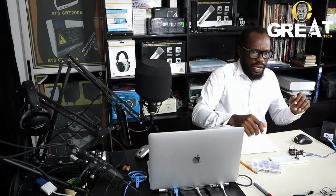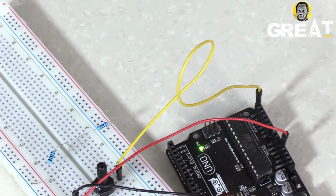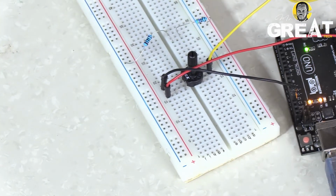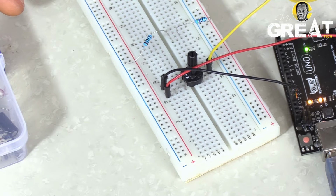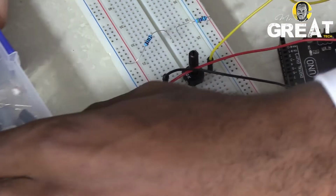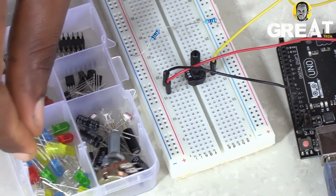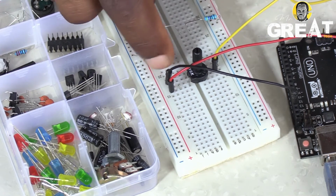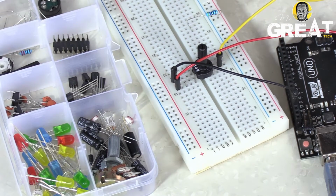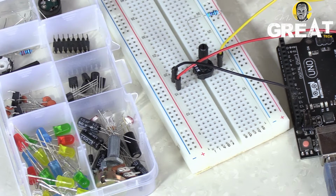Let's connect the hardware, and you have your LED, your light emitting diode. Okay, let me hook up. Let me remove my Arduino so that it's easy for me. You have your LEDs, your light emitting diode. Okay, so you have the red one. Then I have two resistors there, and I'm going to pull out one, the 100 ohms resistor. I'm going to drop it here. Then I'm going to use the 470 ohms resistor, and here you have positive, here you have negative.